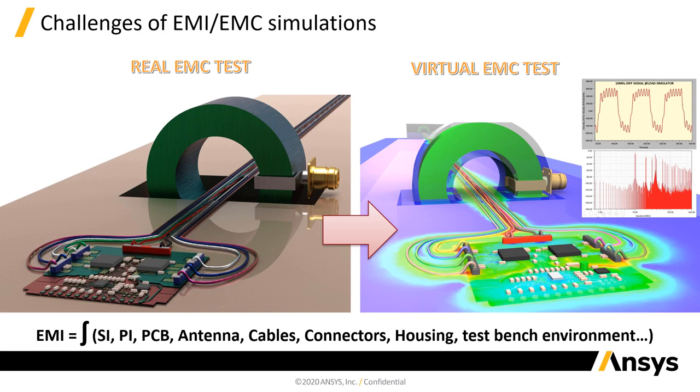You need only information on your design and, of course, information on the environment, such as the BCI probe, the length of the cables, and so on. Most of these details are described in the standards. So we do have in HFSS some 3D components and workflows that help our users to set up these kinds of tests.